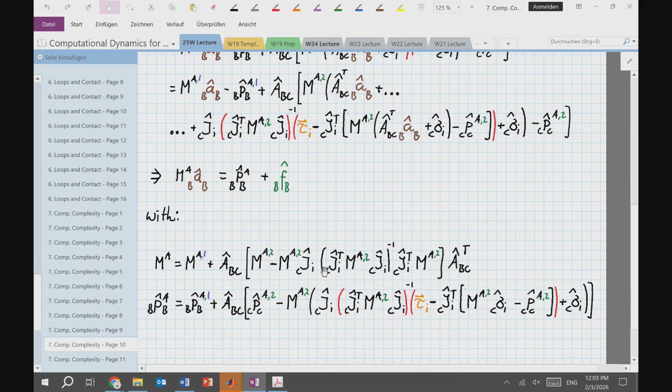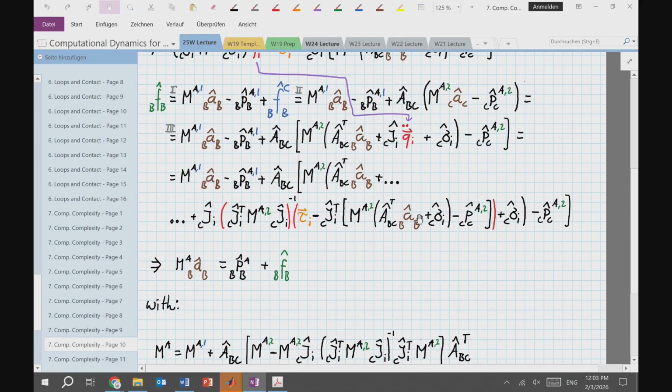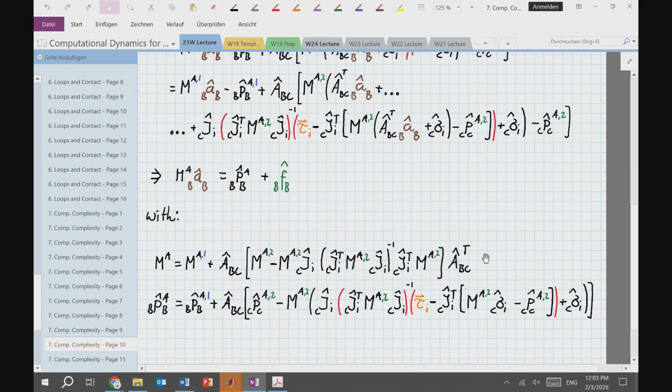And here's how MA is being computed, right? It's a little bit more involved. Because, oh, sorry, I overlooked this one. There's a third quantity, but same story, right? Forward transformation, matrix, backward transformation, Jacobian, matrix, and so on. I missed the Jacobian. Forward Jacobian, backward. Anyway, here's the full term, right? The important thing is this is a 6 by 6 matrix.